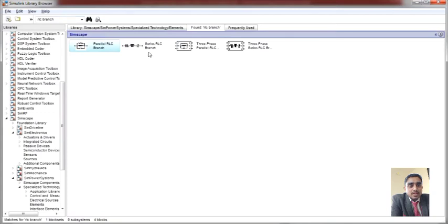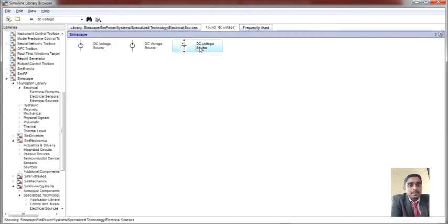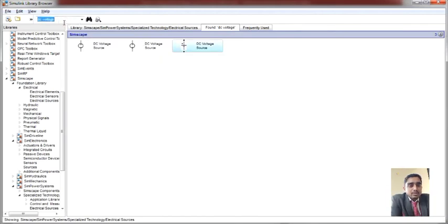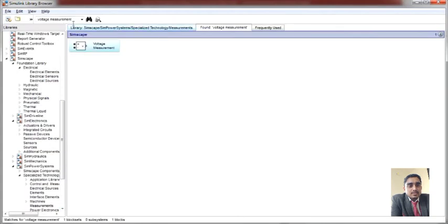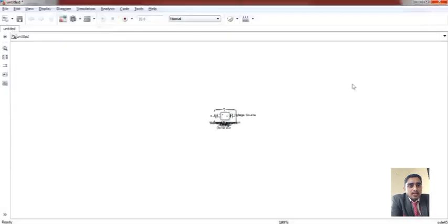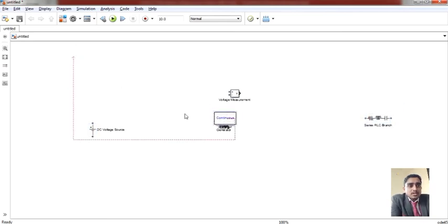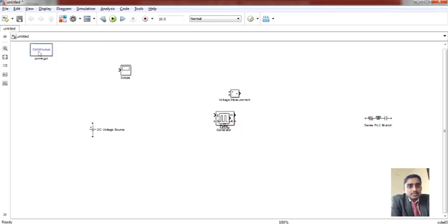I will copy the MOSFET and paste it 5 times and arrange it in an upper layer of 3 MOSFETs and a lower layer of 3 MOSFETs. And in the MOSFET we require only the source, drain and gate pulse, and not the measurement. So I will rotate the MOSFET as required. That is our source, drain and gate.